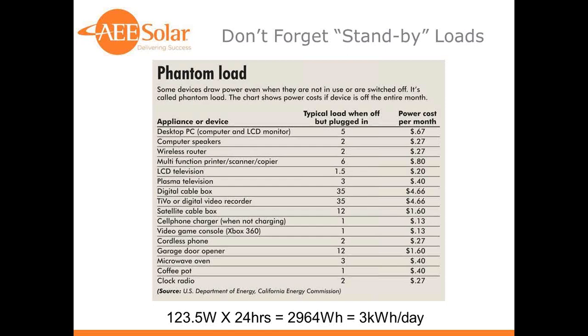Anything that has a remote control essentially has circuitry that is on in the device. It's just waiting for the remote to tell it to operate. So these things can add up. And in this example, you add all these things up, it's about 123.5 watts. And if you run that for 24 hours a day, that's almost 3 kilowatt hours a day. That's a significant amount of energy.